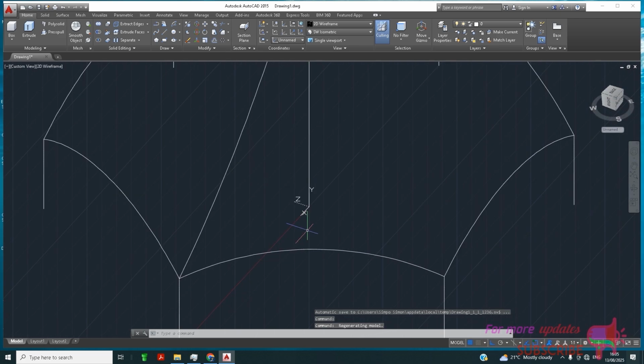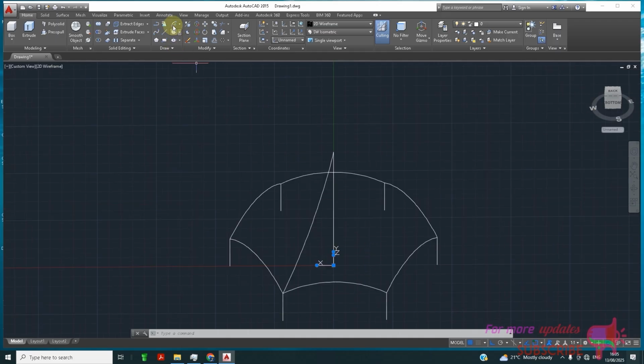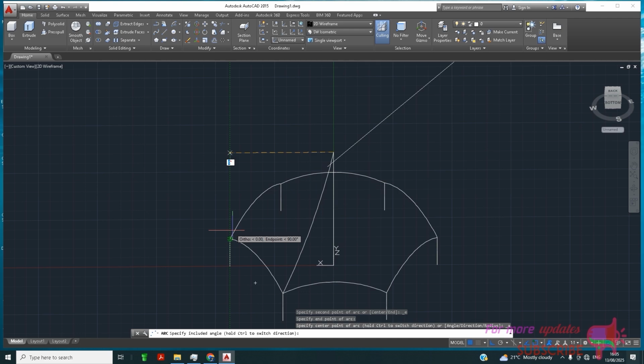And then I will just select my UCS, move the X to that end. Remember, this one I'm restricting endpoint. That's why you can just pick that easily. From that endpoint to that endpoint and then 30.